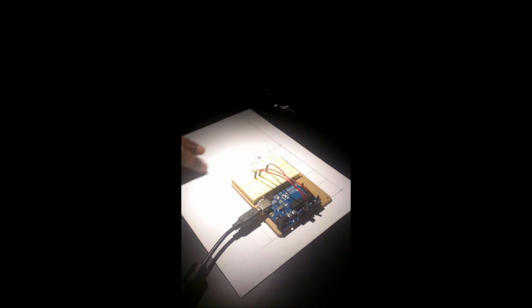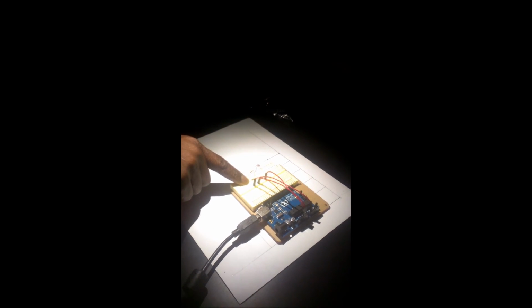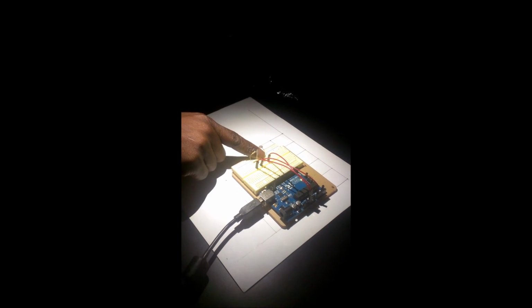And this is the hardware that we use for our system. We have the Arduino right here, and then we have our light sensor right here. In order to protect our light sensor from excessive current, we put a 330 ohm resistor across it so that the current will be correctly regulated. This end of the setup goes to the ground, then we have one wire connecting the light sensor to our analog pin A0, and then we have the third wire going to the ground. So this completes the circuit.